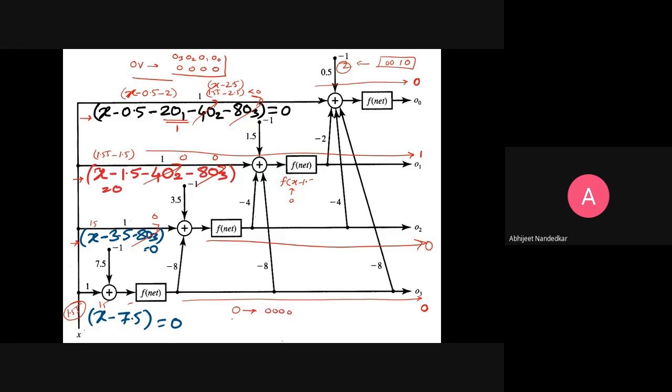When I put in 1.55, you will see that I received 0, 0, 1, 0. So for different input voltages there will be a different code, and for a certain range of inputs, this code will be maintained. Okay, so for 0 code there will be one range. For 0, 0, 1, there will be one range. 0, 0, 1, 0, there will be one range.